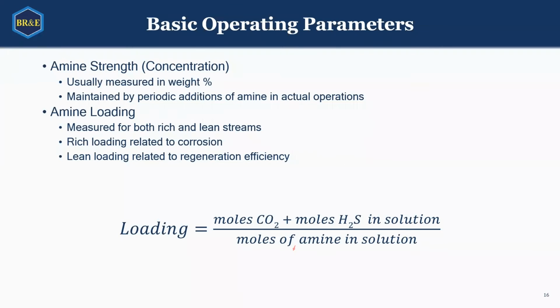So the amine loading is basically how many moles of CO2 or how much H2S. Let's say we're going to be using, for CO2 capture, just CO2 per mole of amine in solution. And there are some maximum loadings, and there are a few loadings that are also connected with that.